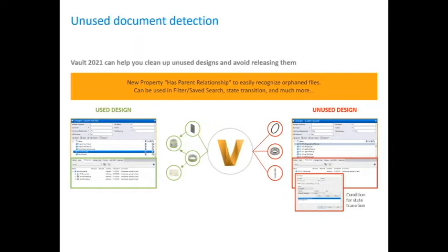Obviously, so in Vault, when we're talking about parents, we're talking about the relationship between components and the assemblies or sub-assemblies above, or the drawing that's associated with that. So that makes it easier to realize, okay, if I've got several components in there, which ones are actually used in assemblies and which ones are just kind of orphaned out there, where we can maybe get rid of those files. So that's a nice thing, which is over and above what you can get in a Windows environment.